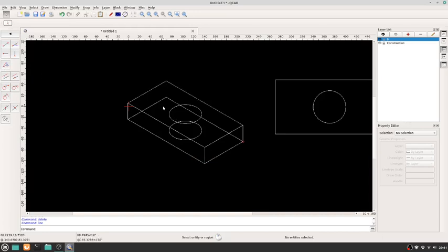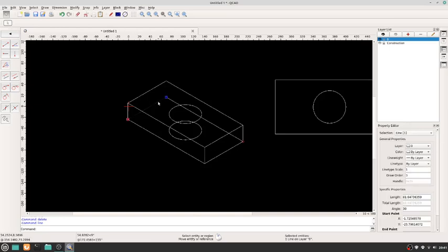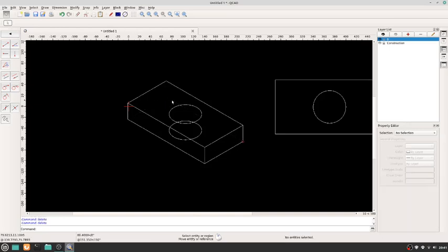And the reason why I didn't do that line is because I don't actually want this as a wireframe. I want it to be like if this is a solid surface, so you wouldn't be able to see these lines behind. So if I'll just delete some of these lines we don't need, and if this was a hole in our block, we would see this little bit here, this segment, if you can see where my cursor is going, my mouse, but not this bit here, because this would be hidden.